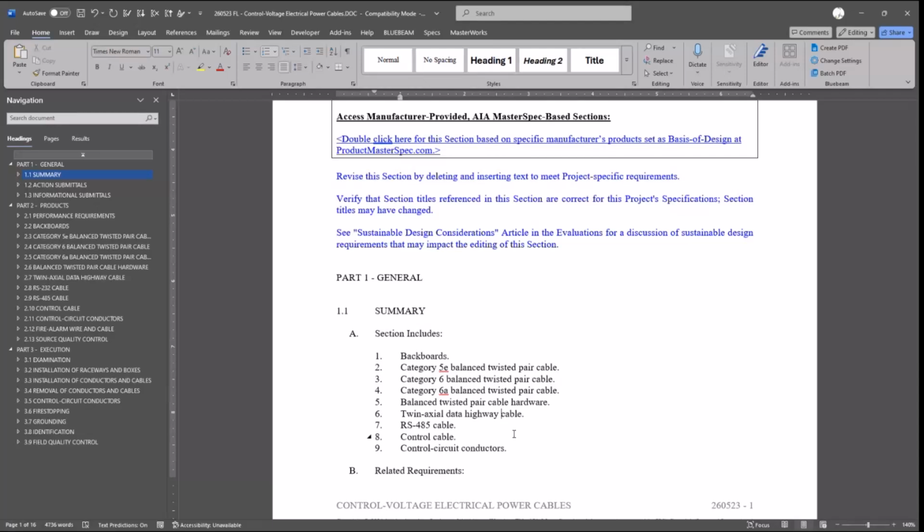Yes. Yep. And for future reference, you can kick it back. You can deny it and say the submittal was not reviewed, submit each whatever under each individual header. That's totally fine. I've kicked back a lot of submittals because of that. On the larger projects, they'll submit 800 sheets across 5 different subdivision numbers under one division header, and I'm like, no, this is not going to work. Yeah.